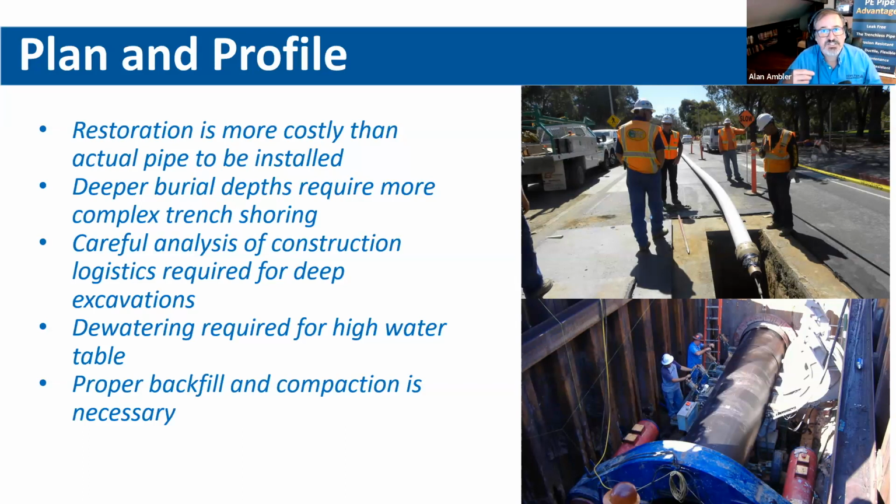When we get into seeing proficiency and productivity in a long continuous run of pipe, if we can shore longer areas, make those excavations, fuse up that pipe run and put it in that deeper shoring, we're going to maximize our productivity, as the actual excavation, and then the backfill and compaction as we go through, are often very time-consuming efforts. Obviously, MOT is going to be an issue in shutting down any type of roadway within a suburban or urban environment.